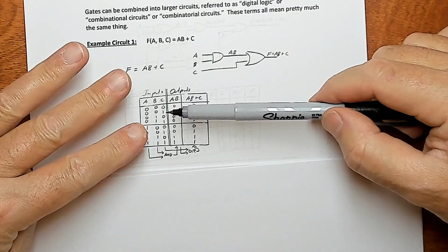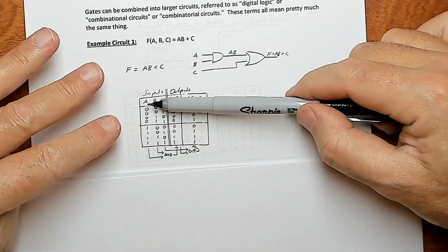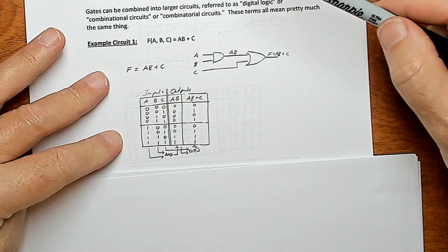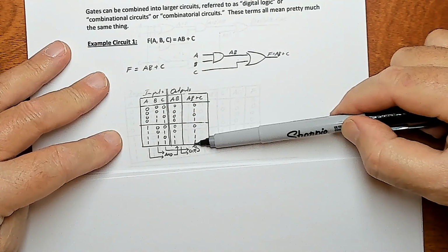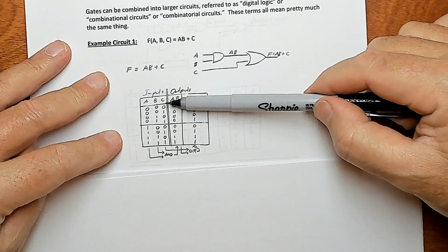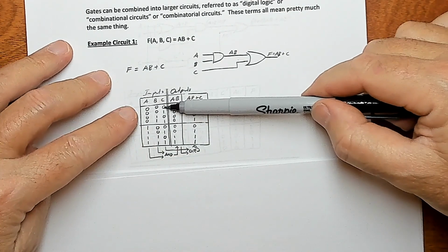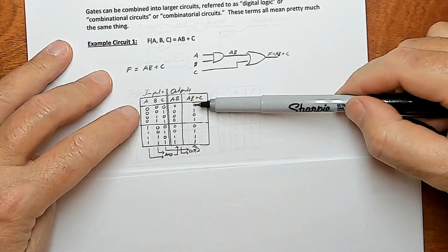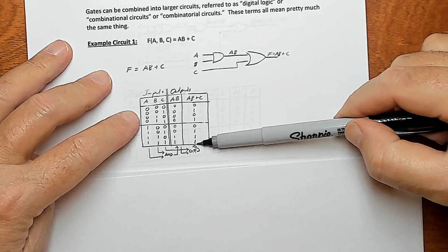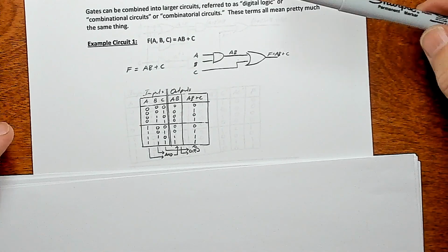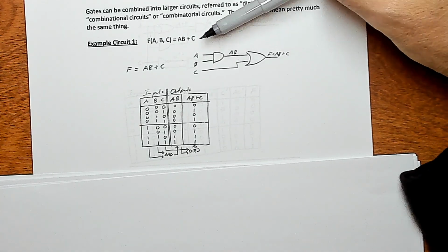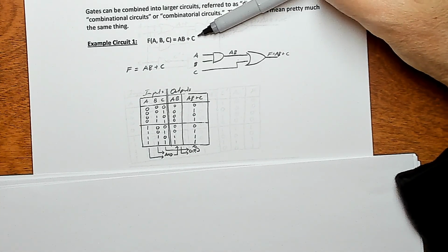So this is mapping a triplet, right? This function is mapping a triplet of binaries, A, B, and C, back into a single Boolean value output. But basically, this table is defining, for any possible 3-bit input, the single bit output that this function will produce. Okay, so kind of what we did is we started with a Boolean equation.